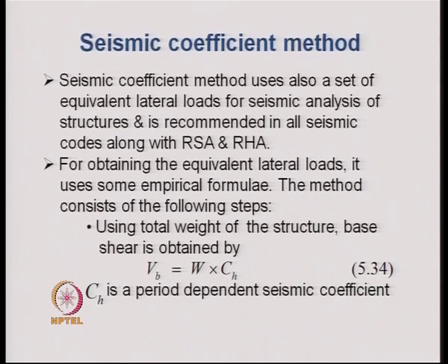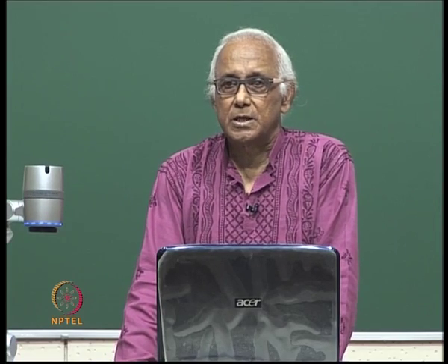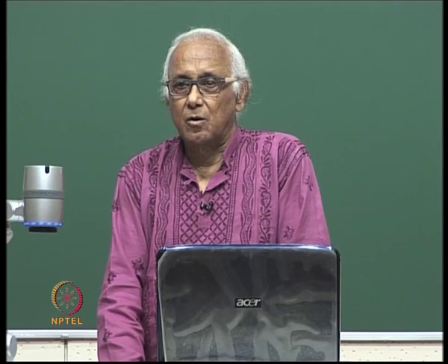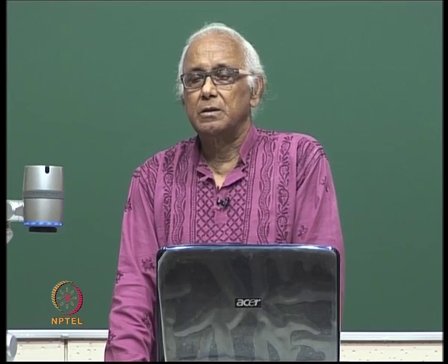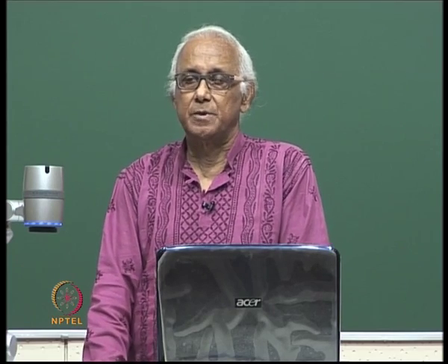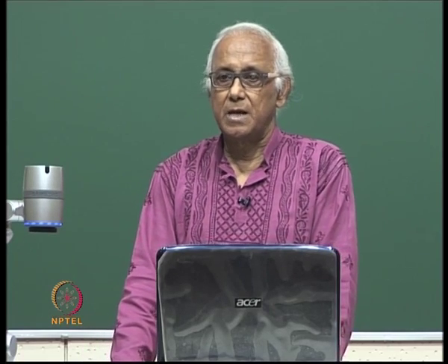The method consists of the following steps. Using the total weight of the structure, the base shear is obtained by this simple formula given in equation 5.34, that is Vb is equal to the weight of the structure multiplied by Ch, which is called the seismic coefficient, which is generally prescribed, and this seismic coefficient is time period dependent.